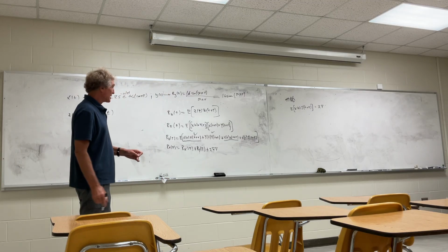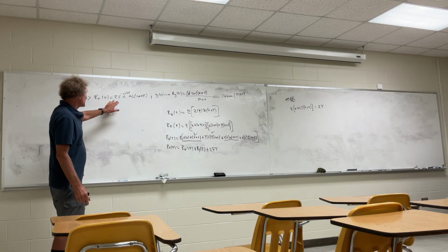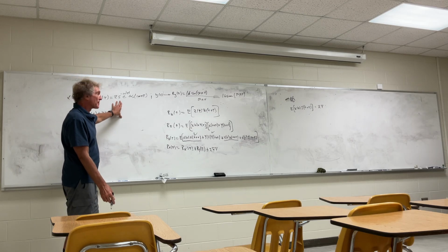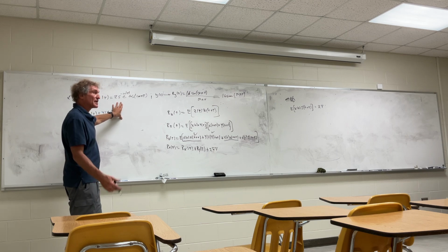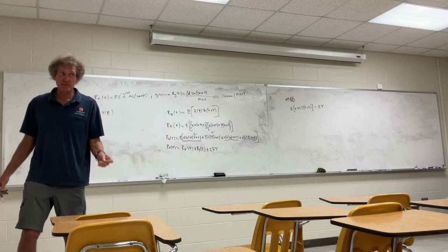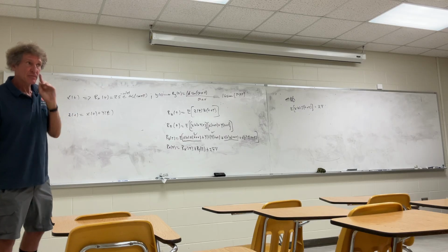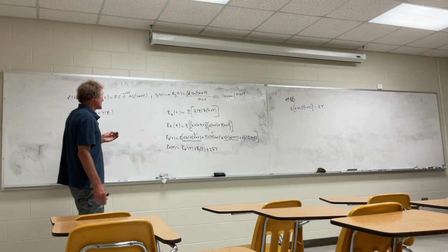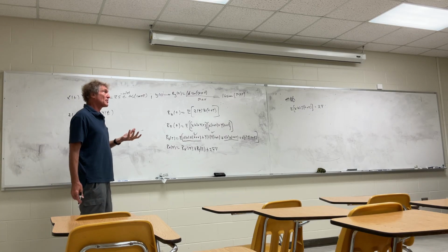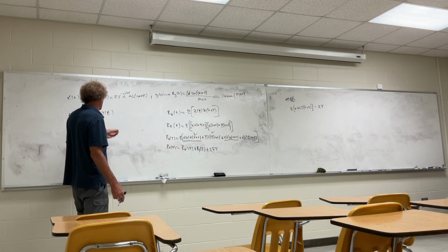Now, I'm not done. Now look at these things. Look at this one. If this is the autocorrelation function, do you remember how we calculate the mean squared value? This is the autocorrelation function of x. Mean squared value of x is? Tau equal to 0. Yeah, he's right. You put tau equal to 0, and what that is, by definition, is just the mean squared value of x squared of t, right? That is mean squared value.